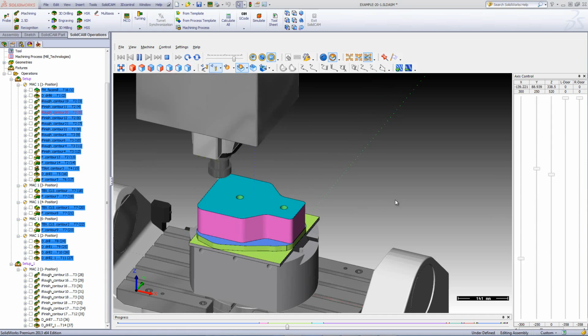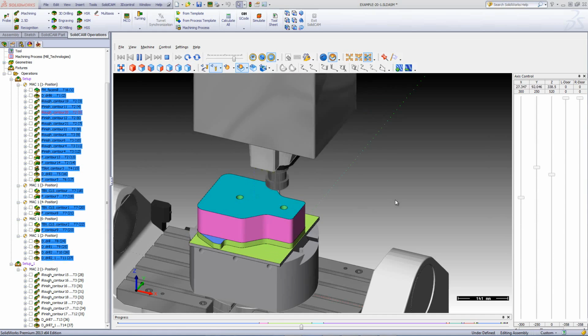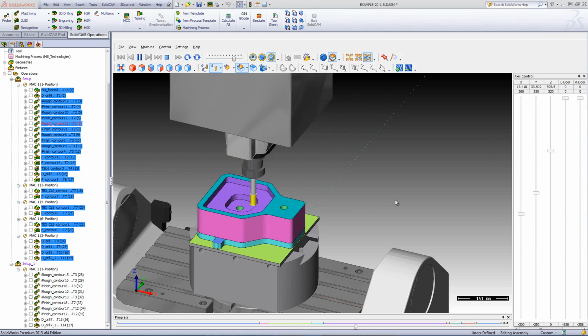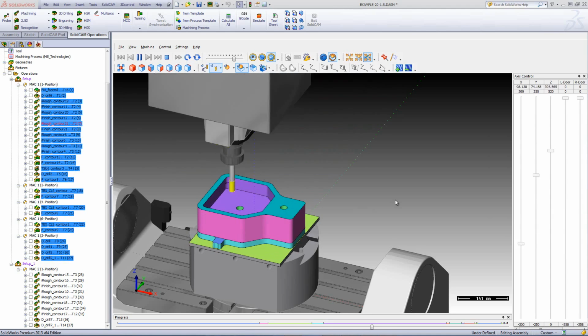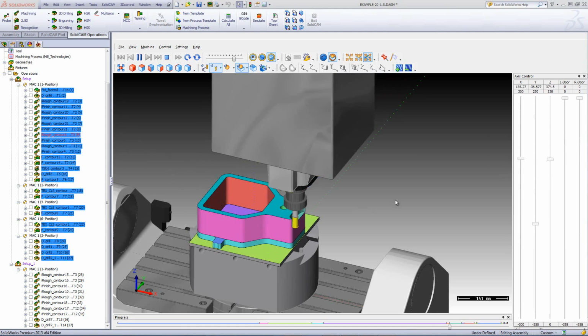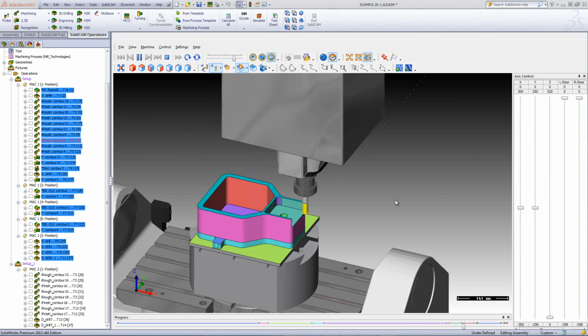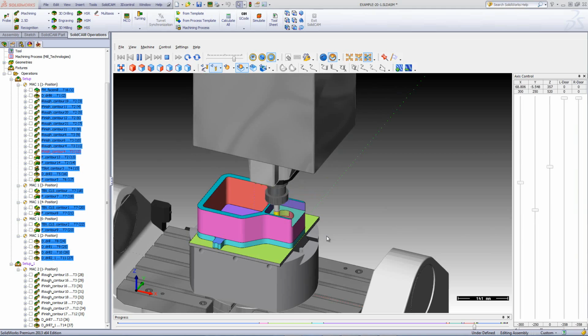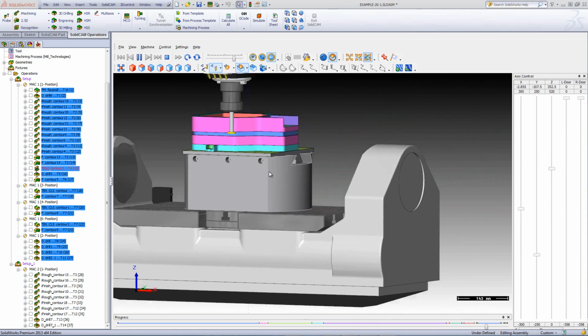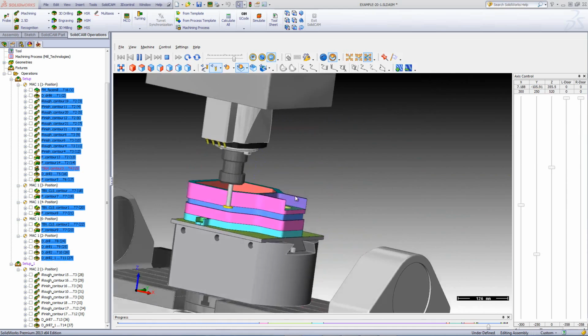Then doing the next area at the very bottom to complete that area as well. Doing that huge pocket on the inside until the very bottom of the part. Finishing off that pocket and then working on the next pocket over there. Next, we're going to start our T-slot around the part itself as shown over here.